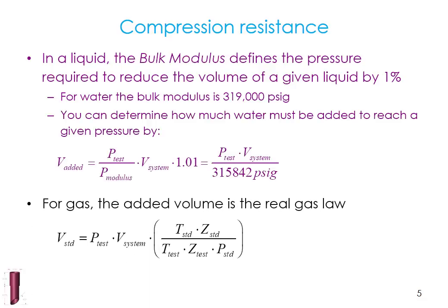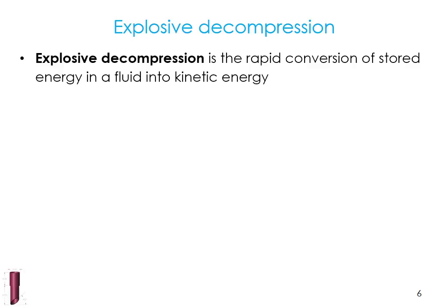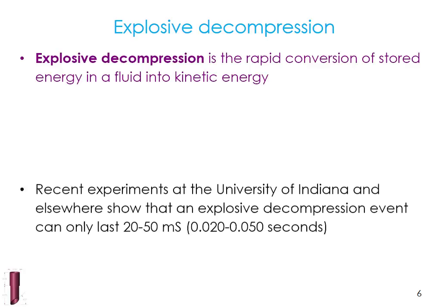For gas, the added volume is the real gas law. So it's test pressure times the volume of the system times the conversion to get back to standard conditions. Explosive decompression is the rapid conversion of stored energy in a fluid into kinetic energy. Rapid conversion is the important part there.